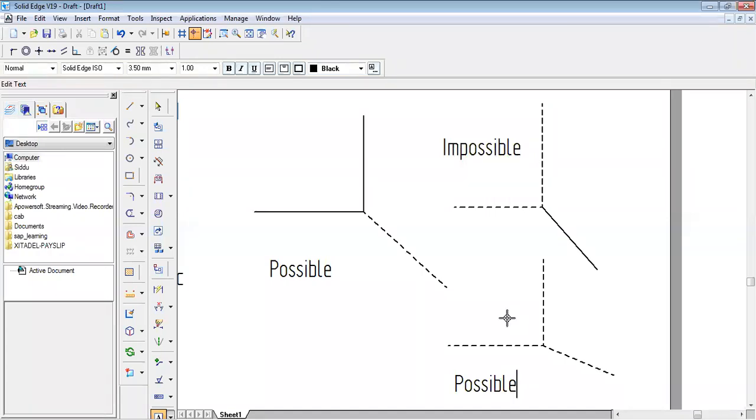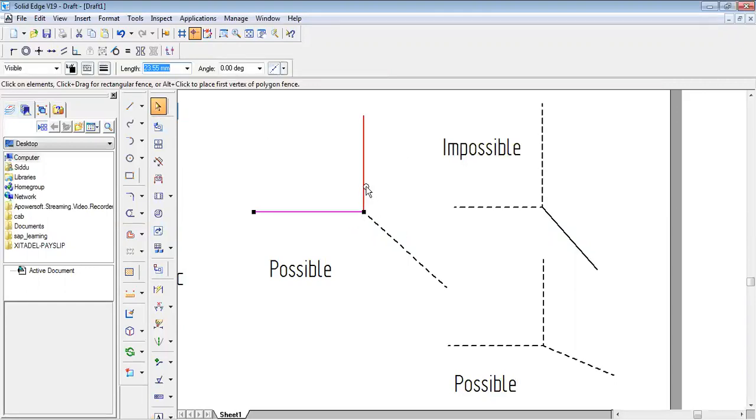If you have two seen edges, one unseen edge can pass. If two seen edges are connecting, an unseen edge can pass from that. But if you have two unseen edges, you cannot come across a seen edge passing from that. This is impossible. But of course, if you have two seen edges, the edge which is passing from this should be unseen edge only. Okay. So now with this, we will complete the last portions of the problem.